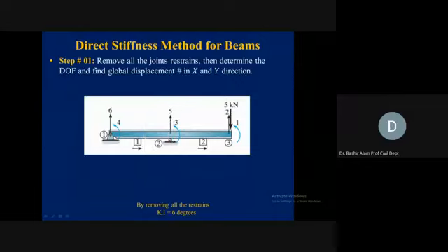And the member node numbers 1, 2, and 3, from left to right we are moving. Again, these are arbitrary, you can take any node numbering which you like. Member 1, here you see from node 1 to 2. Now, remember, if we write the addresses of the element 1 stiffness coefficient matrix, what will be the address?